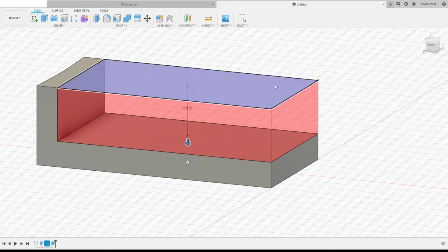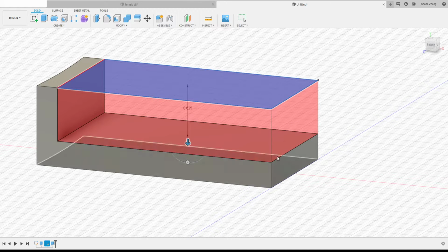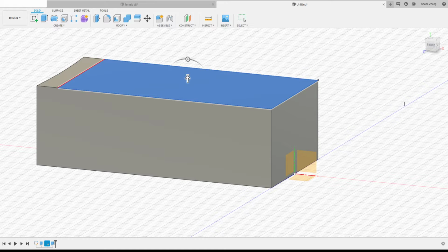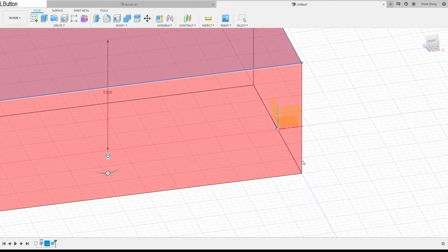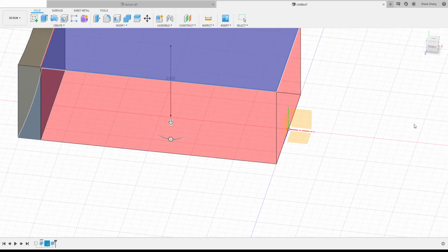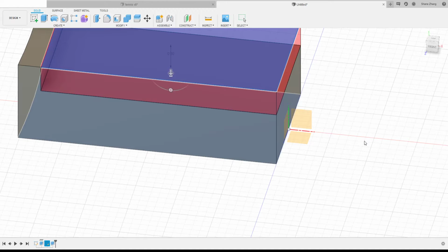We would start from this plane, and extend is not a distance, so we're not gonna extrude a fixed distance. Instead, we're gonna extrude to a point that is 7/8 to the bottom plane. So from the icon, you can tell it kind of looks like this, to object. So let's give it a try. To what object? Right, so we're gonna extrude it to the bottom plane, but not all the way to the bottom plane. So that's why we can set up an offset. So not exactly all the way to the bottom plane, but 7/8 to the bottom plane.